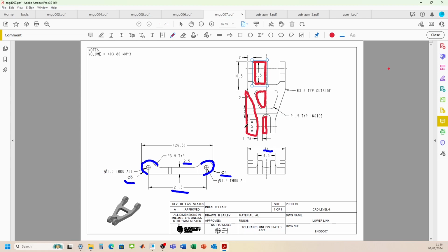And then because it's symmetrical, if I only model half of it, then I'll be able to just mirror the rest of it once it's completed. Okay, so it's going to be draw the outline of the shape, extrude it, and then we use another extrusion from a different plane to cut out these shapes. We'll probably use the line tool to generate the geometry that's needed, and we'll worry about the rounds afterwards. Okay, let's head on over, have a look how we can do that.